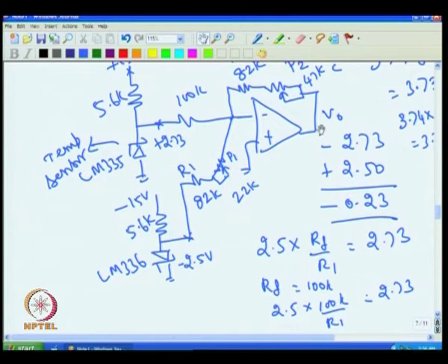This can be plus or minus. For example, if this temperature drift is plus, then it will go reducing, if it is minus it will be increasing. So, we will say that my temperature measurement can be accurate only to plus or minus 0.75 degree, if I consider the drift due to this Zener alone.